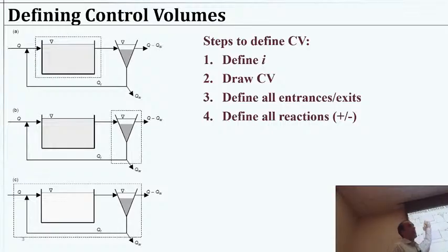One could be a wastewater plant where we have some biological treatment here, followed by a clarifier, and then we want to separate all the bacteria that we're growing and let them accumulate into some sludge, sedimentation chamber, or clarifier, whatever you want to call it. Then we have some cleaner water leaving, some dirty water coming here to go to the waste, and then maybe recycling some.